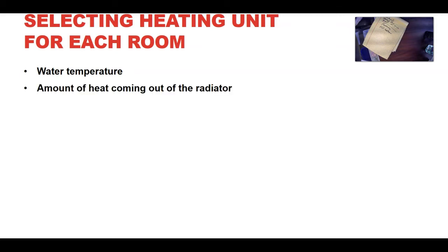And I say hot water system because hydronic could also be steam, depending on which industry you talk about. Okay, so selecting the heating unit for each room. It depends on the water temperature that you are planning to provide for that room and the amount of heat coming from the radiator. Also the length of the radiator.